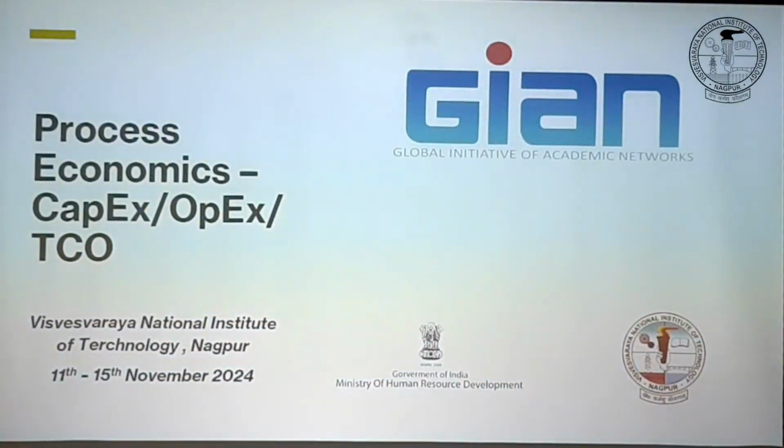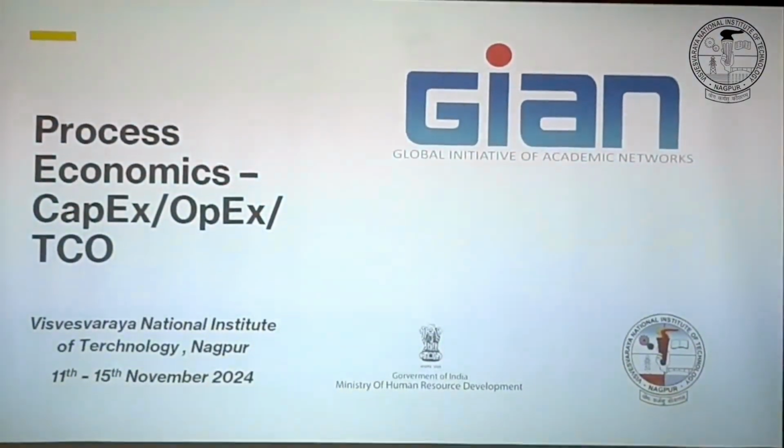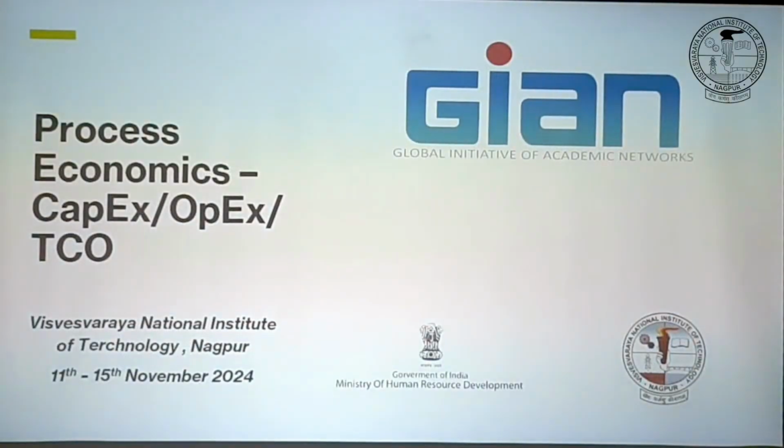We talked a lot about operating expenses and capital expenditure. We looked in detail at how we estimate capex, equipment costs, procurement costs, construction costs, and how we calculate OPEX. For this we already saw many examples, such as: if the cost of natural gas is 30 euro per megawatt hour, how we calculate, based on LHV efficiency, what the power price will be.